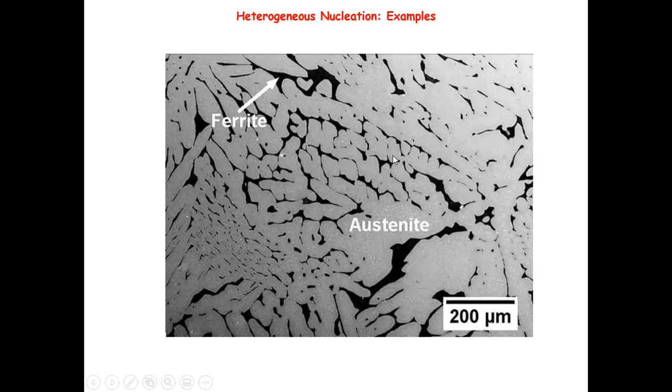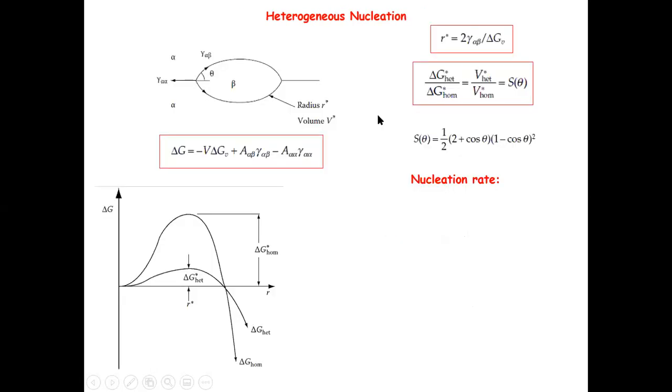You probably wouldn't be able to see the grains, but you definitely see some of the grain boundary features, like these small grains and these large grains. All these black things actually nucleate on the grain boundary, right? We don't see the grains because this is just an optical image. We don't see the EBSD contrast, but we're looking at something like this. So this is an alpha grain, this is an alpha grain, and this one is forming on the grain boundary.